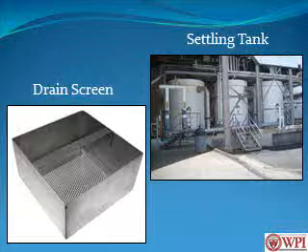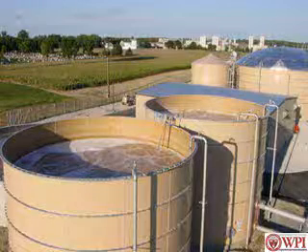Separation uses drain screens, settling basins, berms, and other similar methods to separate waste products from the wastewater before ultimately discharging to the sewer system. Another existing technology is biotreatment with either suspended or attached growth microorganisms. Both aerobic and anaerobic technologies are used for treating this type of wastewater.